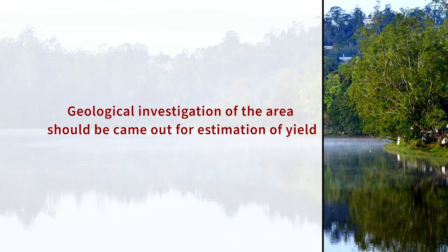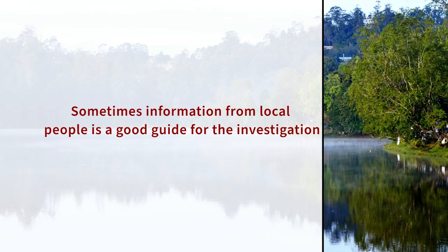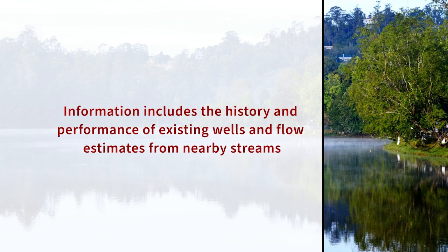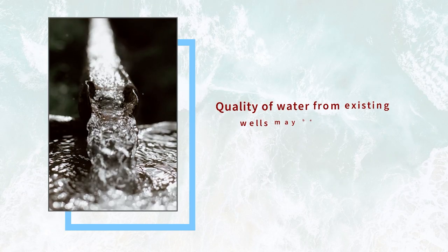Geological investigation of the area should be carried out for estimation of yield. Sometimes information from local people is a good guide for the investigation. Information includes the history and performance of existing wells and flow estimate from nearby streams. Quality of water from existing wells may be analyzed.